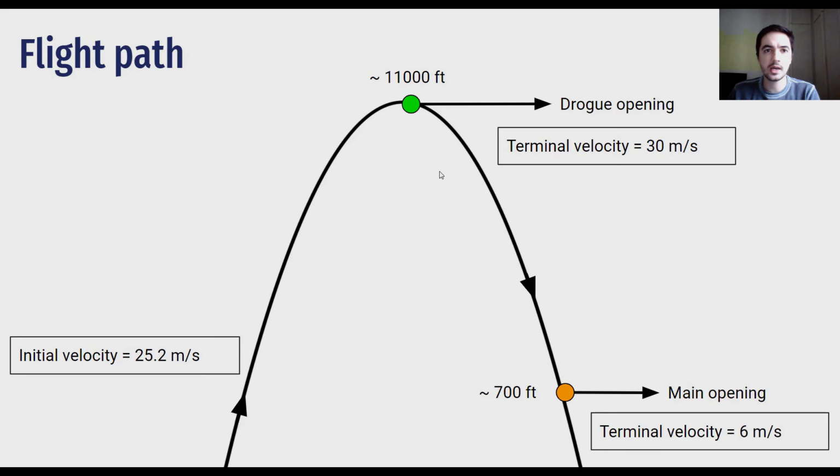During the flight, the altimeters are able to read the barometric pressure and determine the rocket's altitude and its consequent velocity. This way, when the rocket reaches its apogee, both altimeters, for redundancy, activate with some time delay between one another the explosive containers attached to the bulkhead closer to the drogue parachute, splitting the rocket into two parts so that the parachute can open. Then the rocket is lowered down until it reaches the terminal velocity of 30 meters per second.